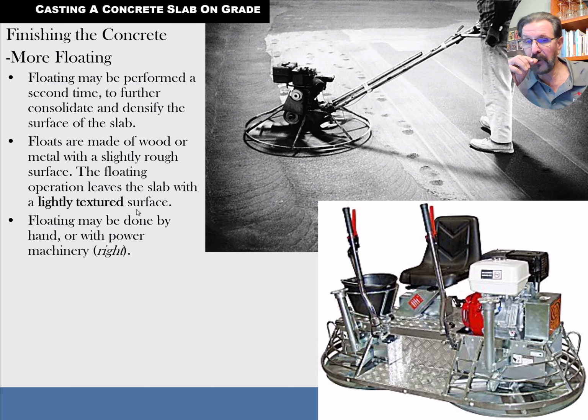So with roadways, parking lots, driveways, and carport surfaces, we really don't want to make a super smooth surface. We want it to be flat, but as soon as you finish floating it, maybe you put a light or a coarse broom finish on it, depending on what you're after, to give you some traction. But you don't want to keep troweling it. The more you trowel and mess with it, the concrete's setting up as you go, and you are making it weaker, not stronger. You are making it flatter, though.